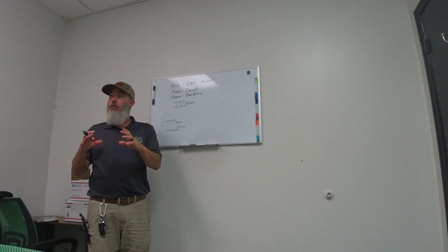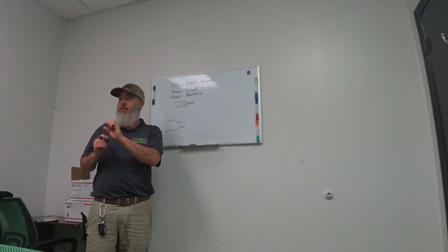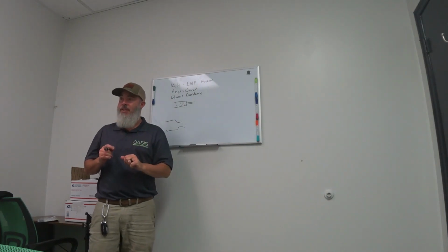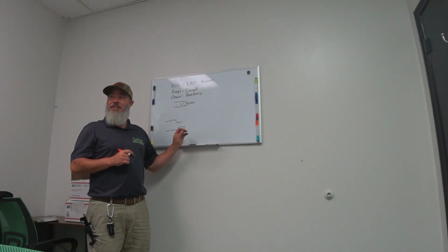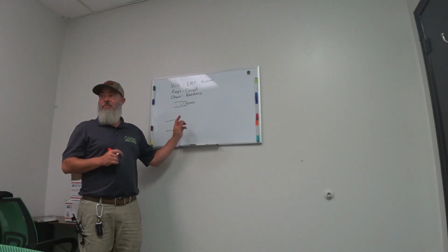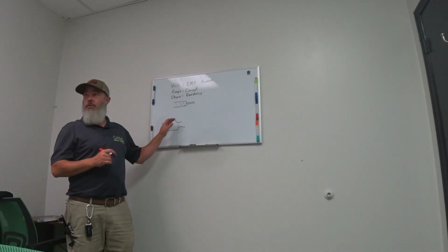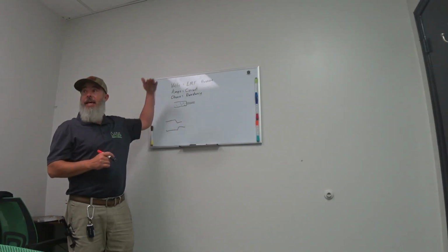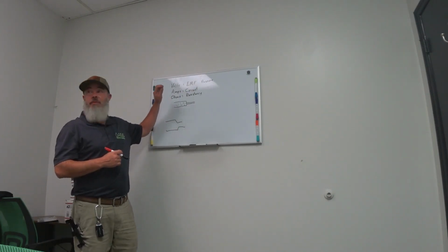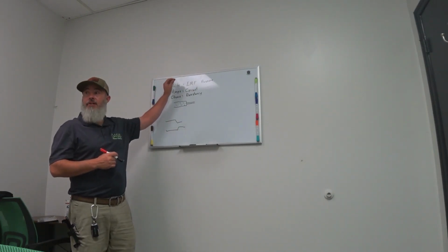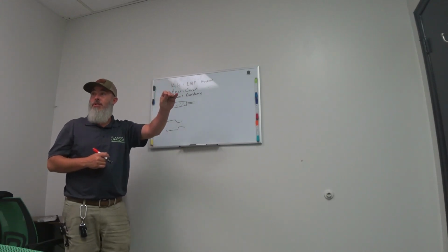Because if you look on the board, you'll see there are these tiny little relays. Because you stepped it down to 10 volts, it can pass power easily out to other low voltage relays that can close contacts to pass high voltage.